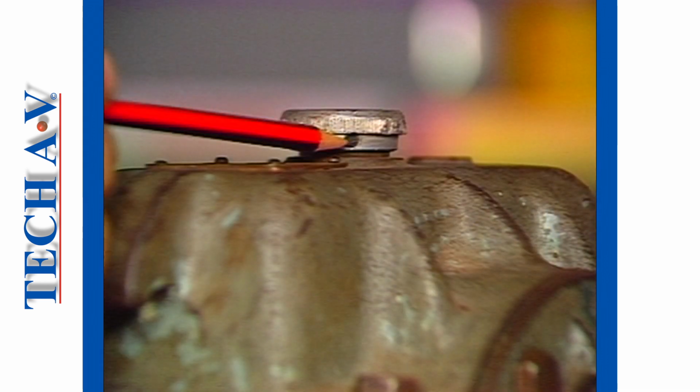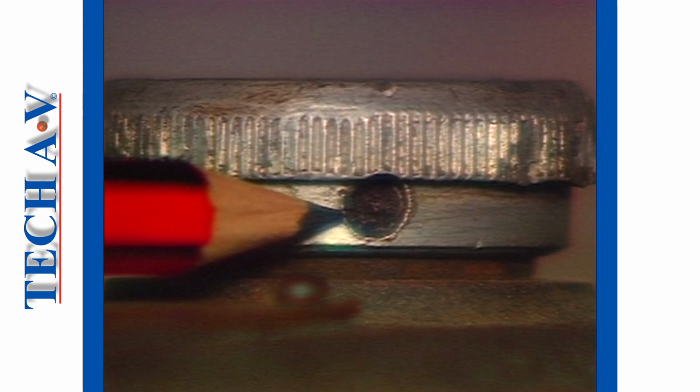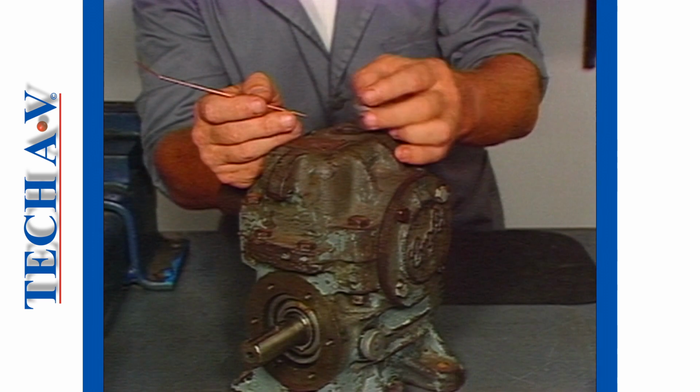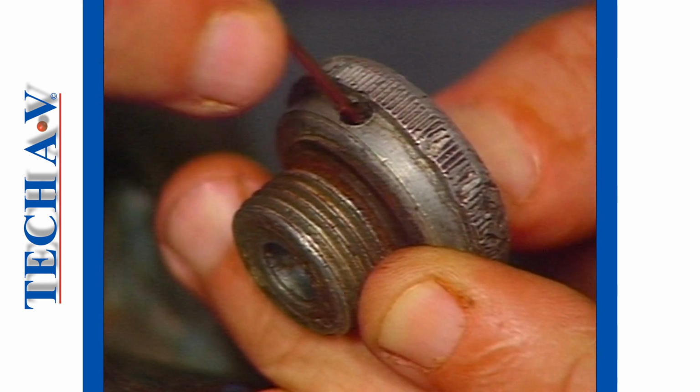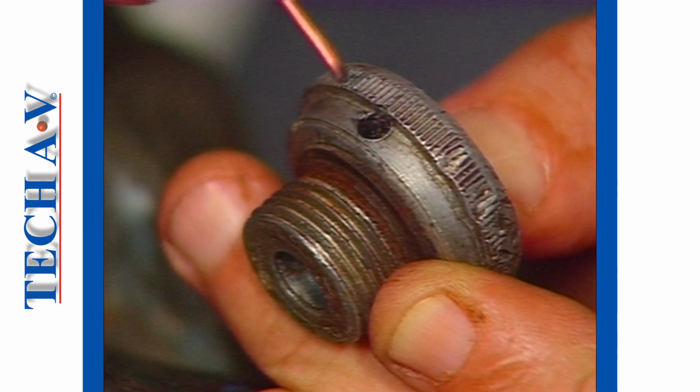It is advisable to check the machine for problems such as clogged vents or breathers. Such a condition will cause high internal pressures, and this is a common cause of premature seal leakage or failure.